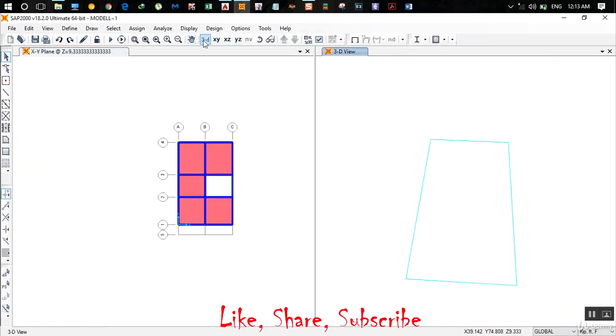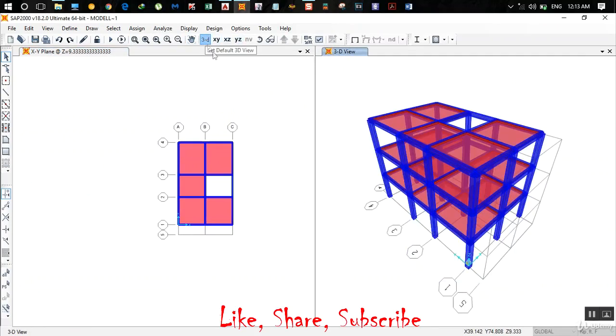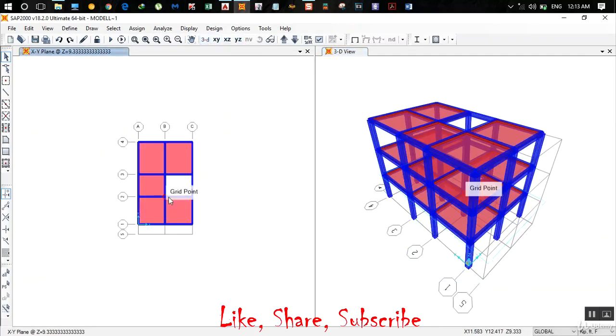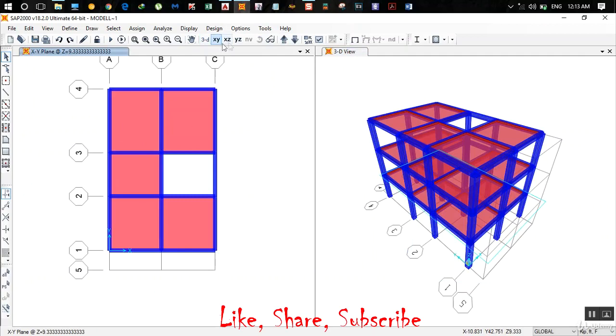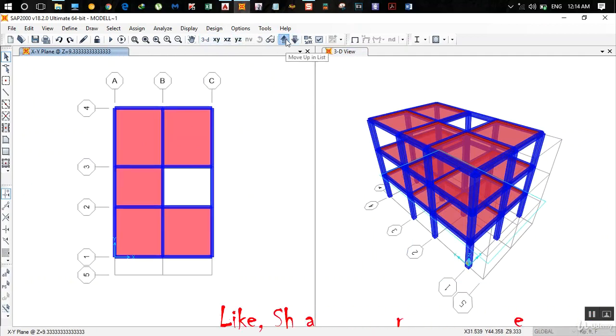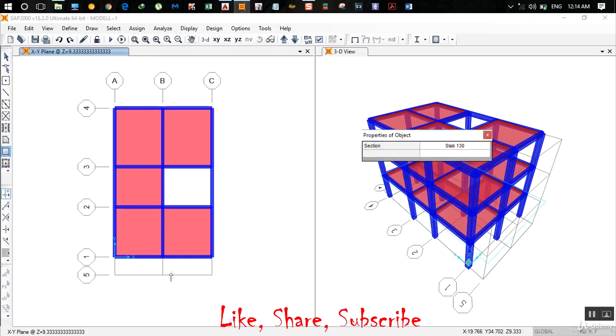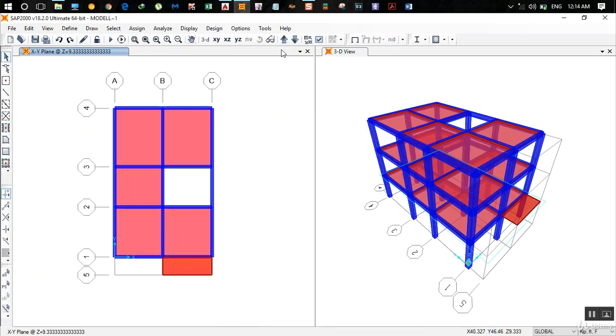So our 3D is missing. So hit this window and click on 3D. Alright. Okay, so this is the first floor, and we got in the second floor. We again draw a rectangular area. We got a slab here. Again, we go one step up on the roof.